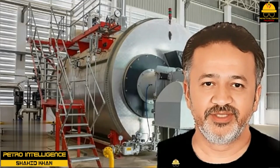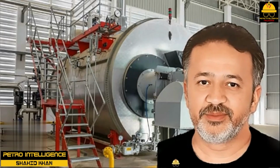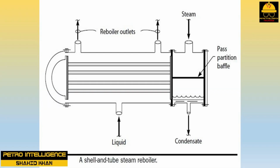Steam reboilers. When considering the steam side of steam-heated reboilers, it is best to think about the reboiler as a steam condenser. The steam, at least for a conventional horizontal reboiler, is usually on the tube side of the exchanger, as shown in this picture. The steam is on the tube side, because the shell side was selected for the process fluid.